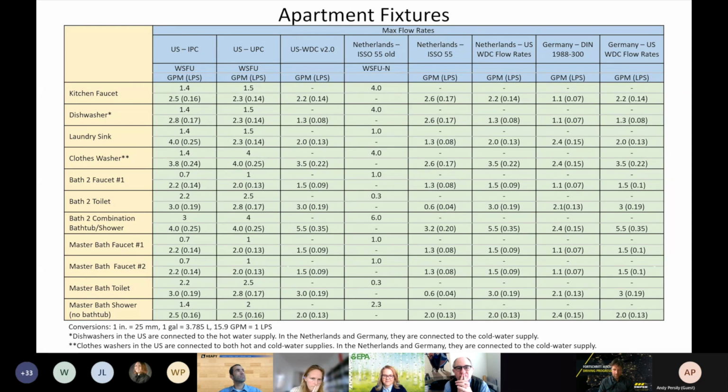You have to have so many number of fixtures to begin with to have at least 2 operating simultaneously. So, for example, I think the flush valve curve starts at the fixture unit of 60. So all Hunter did was extrapolate 60 all the way down to the lowest fixture unit value, which was 4.